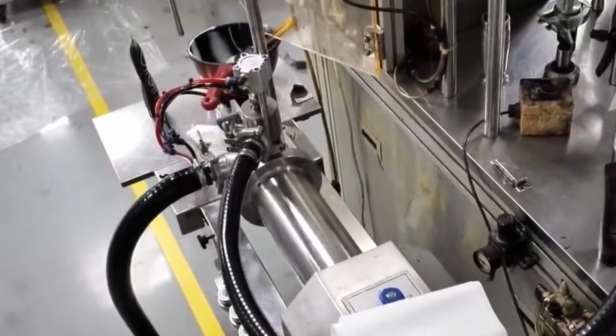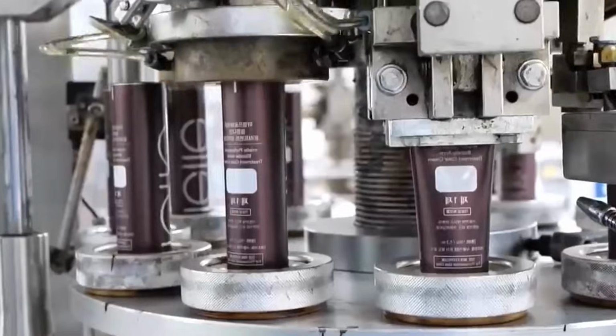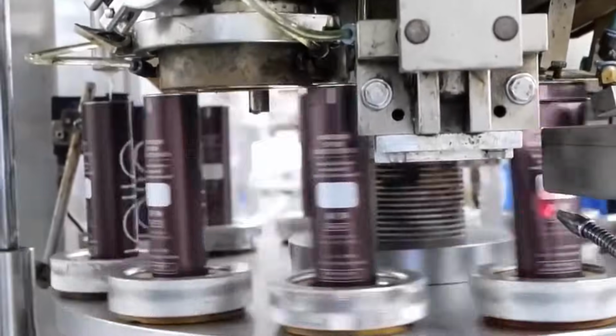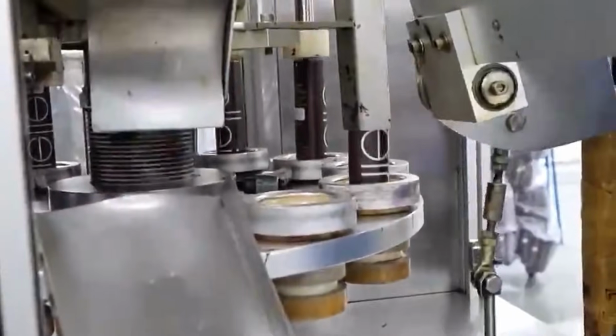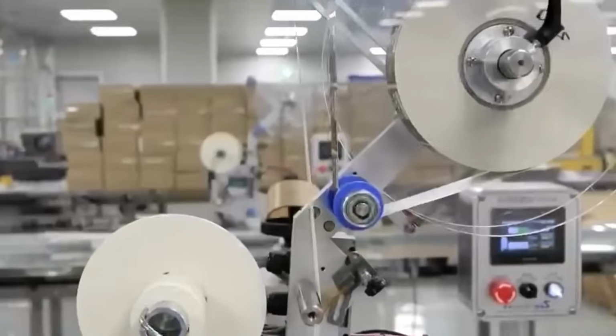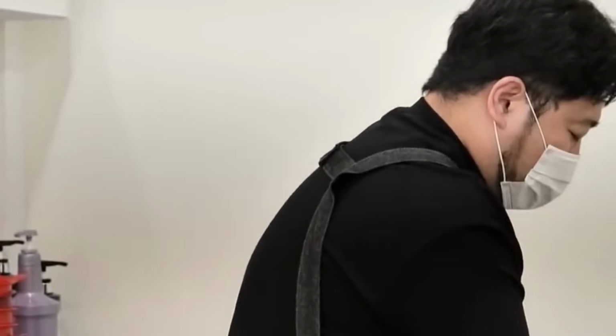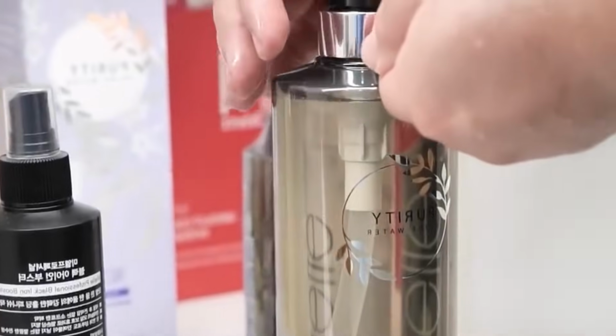Chelating agents such as disodium EDTA are introduced to bind metal ions present in water or raw materials. These are added early in the process, usually dissolved in water, to improve product stability and preservative effectiveness. Dosing is managed using precision pumps due to the low concentration required. Preservatives are added once the surfactant system is fully established.